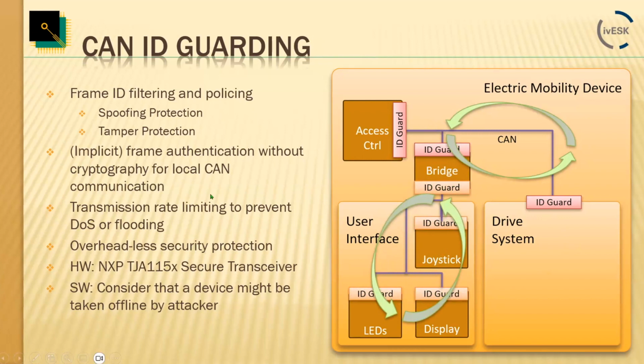Of course, this can also be implemented in software, with the only downside being that with regular CAN controllers, a node will not be able to destroy a message and kill it, but it will be able to recognize it, and we can then implement some mechanism to decide what to do with this information if we detect such an injection.